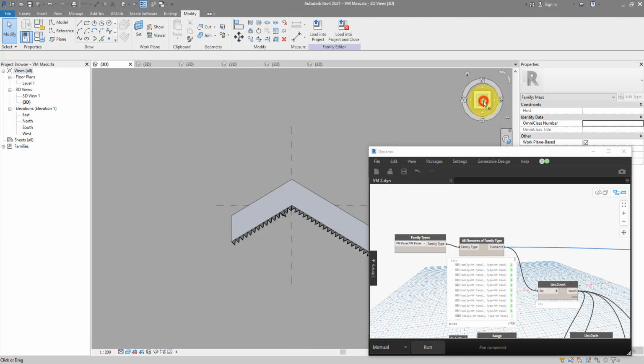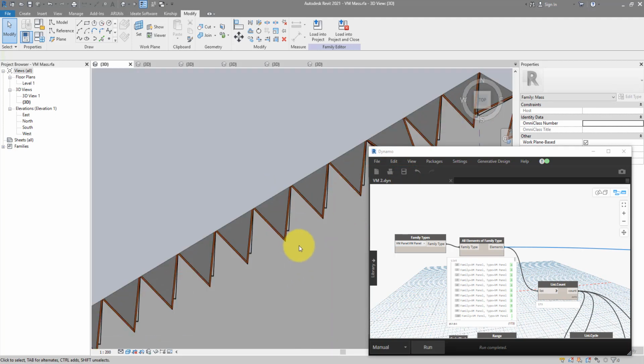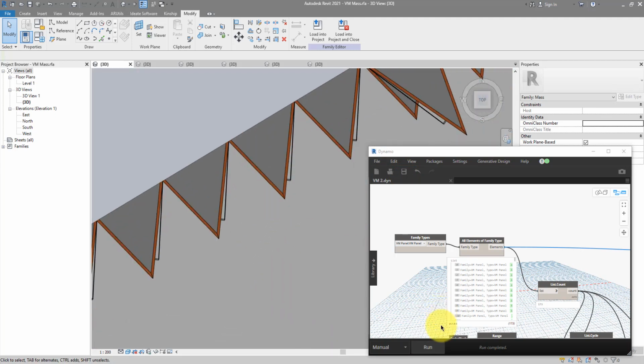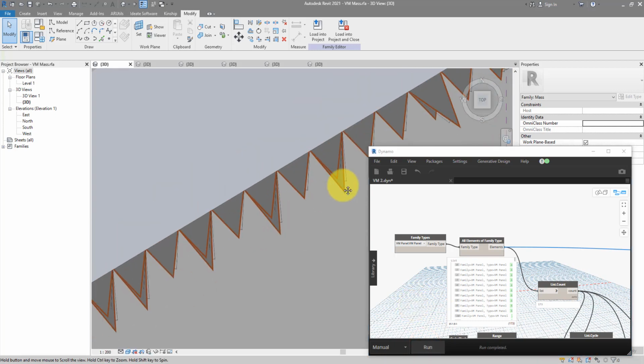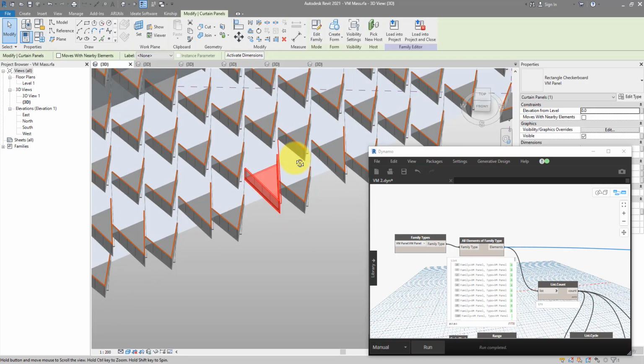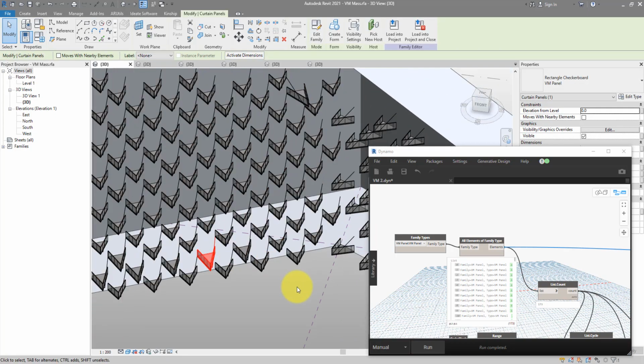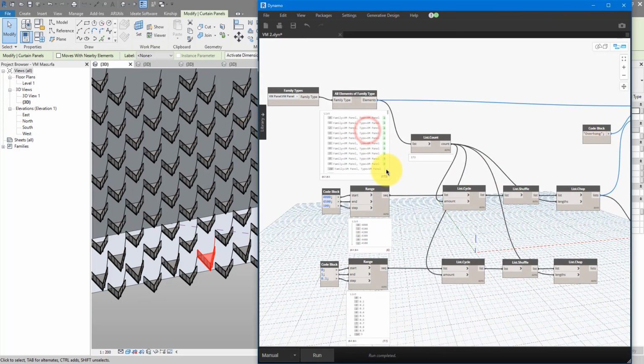If I look into the top view first, you will see they now have the same overhang amount. Let's run this, see what happens. Straight away you see now, much better looking effect, because now those overhang amounts are varied from balcony to balcony. We can now do the same for param 1. If you try to do that with the same node, however, it will fail.